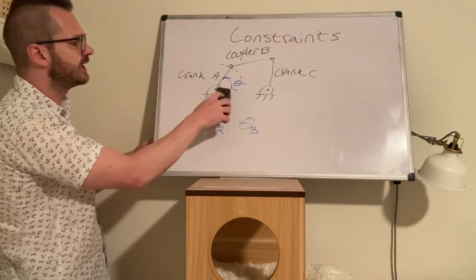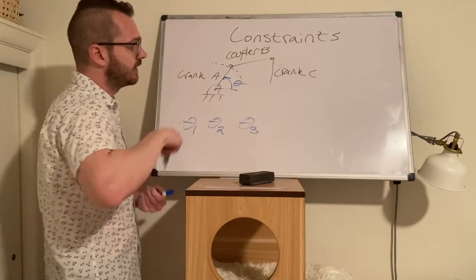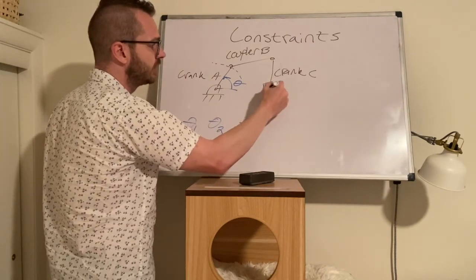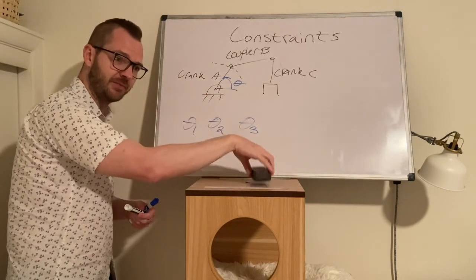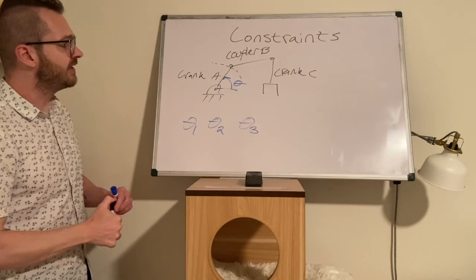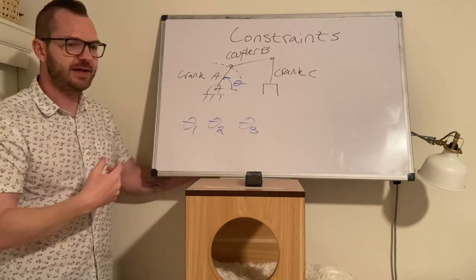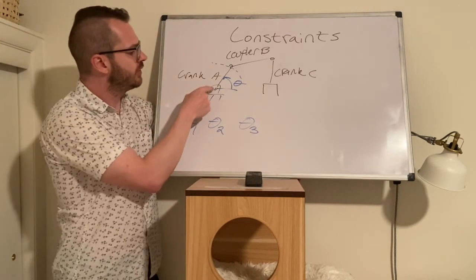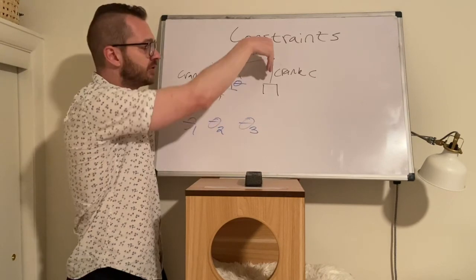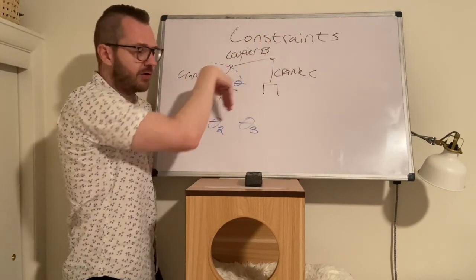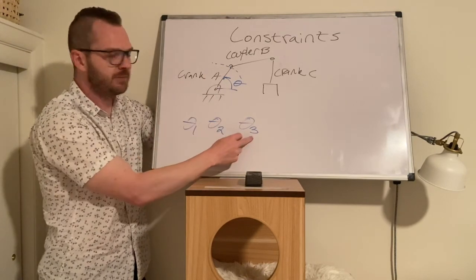You can imagine if I erased this pin joint, and instead of having a pin joint there, we turned it into maybe a robotic arm, right? That arm's going to come down, it's going to pick up my eraser. In this case, these three angles, theta 1, theta 2, theta 3, are in fact independent of each other. You could hold the first joint and the second joint fixed. You could activate the motor at the third joint, and that would lift that third joint. So in this case, each of these become independent.